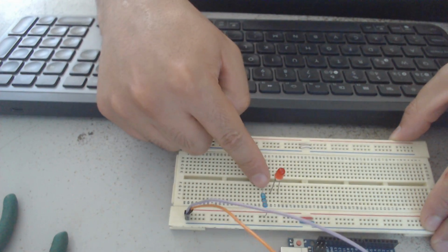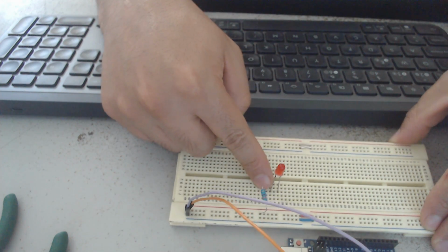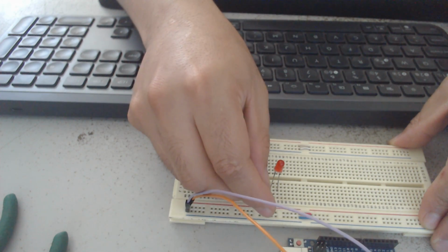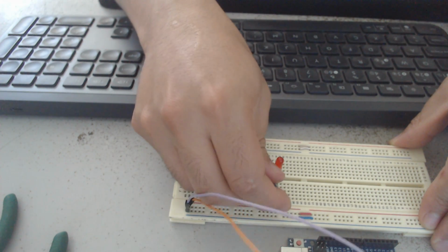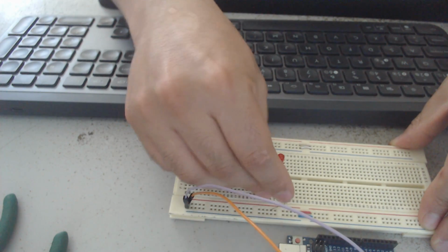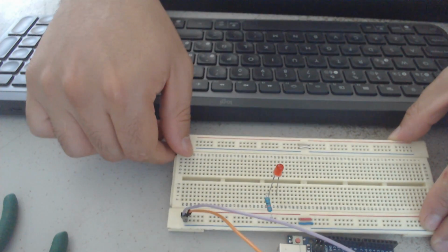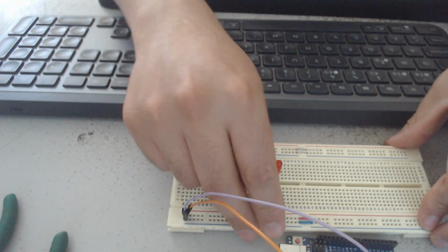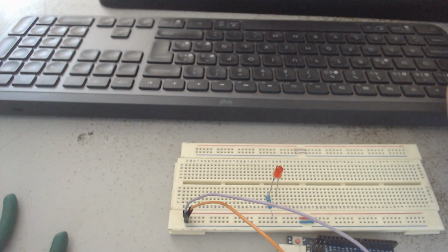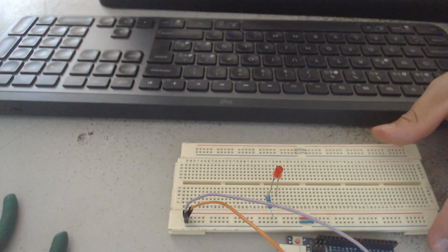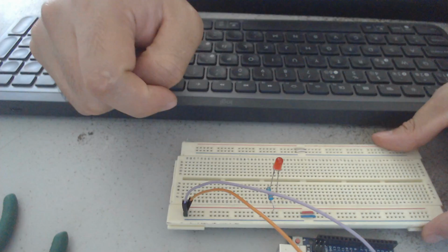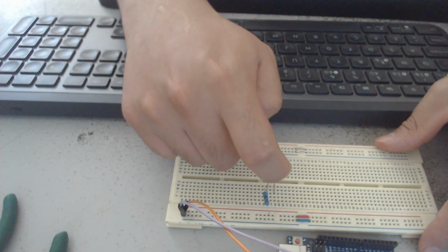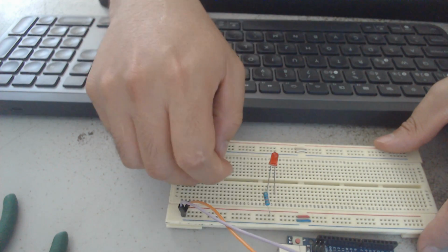So if now my positive leg is on line 42, I need to move the resistor to line 42 because I need to provide the previous electrical connection. So the numbers are not important, okay? In my examples I may use some numbers, and you don't need to follow the numbers. You need to follow the electrical connections. Now we still are missing the connection from the negative to the blue line.